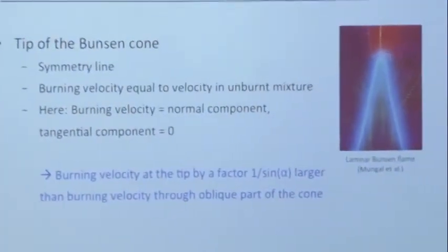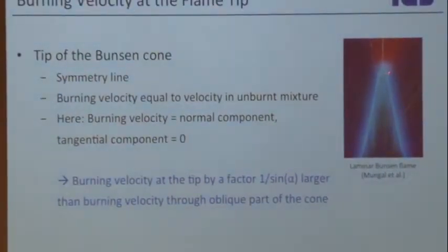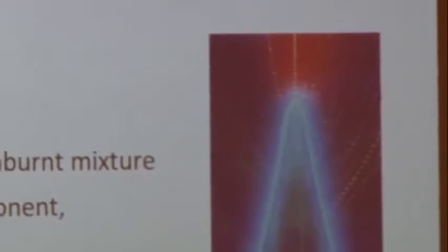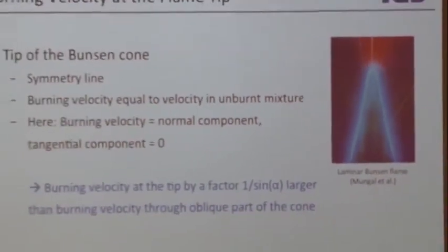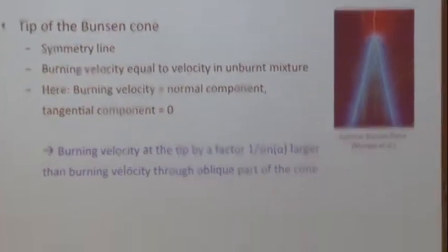other effects are important. The curvature effect here is important. It turns out that the curvature here becomes of the same order as the flame thickness, and then the curvature can affect how the flame burns. Okay, that's important. We said earlier the flame is thin, and if the curvature radius is much, much larger than the flame thickness, then the flame doesn't know about curvature. They have to be of comparable order, and then they can influence each other.